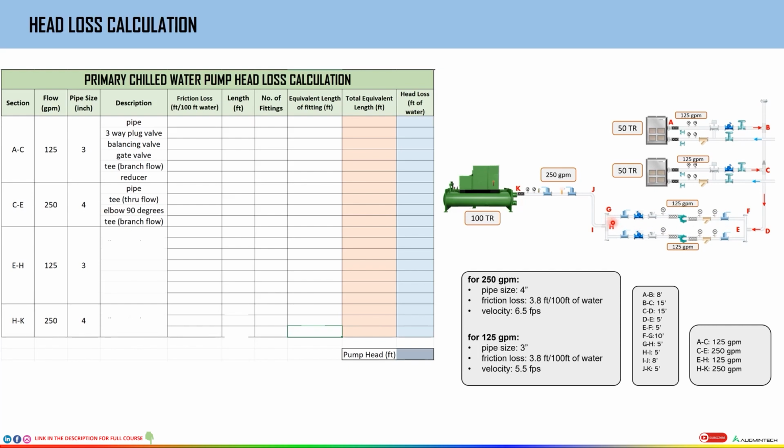And again, we have the 90-degree elbow, but that is something we have already taken earlier. And then we have this T. So we'll just mention all these components over here. We have the pipe, then the 90-degree elbow, then the butterfly valve, then strainer, check valve, balancing valve, and then this final T over here.